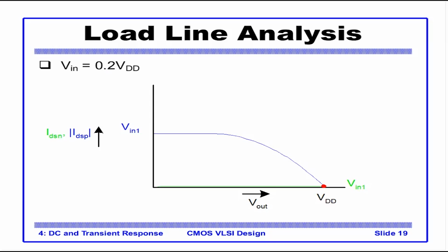So V out is again VDD, obviously on this line. Since the voltage does not cross VT, the NMOS does not start conducting. There is a very faint green line here which we won't see in this graph. We will see that in the next one.